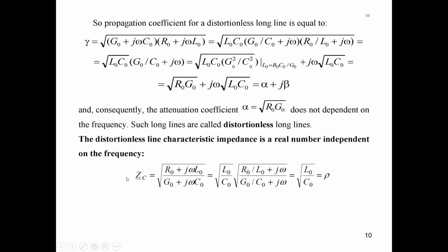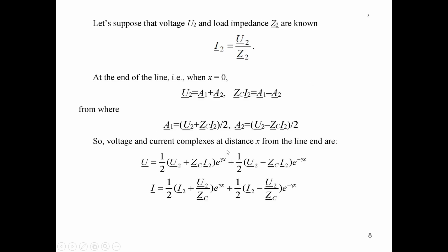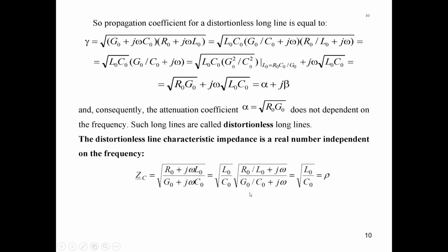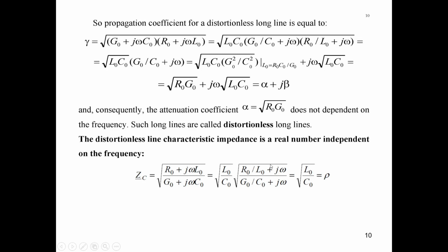And in such a case, not only the attenuation coefficient, but also the characteristic impedance will not depend on frequency. Why? We can substitute into the designation of characteristic impedance this condition, and rearranging this equation, we will have such an expression.